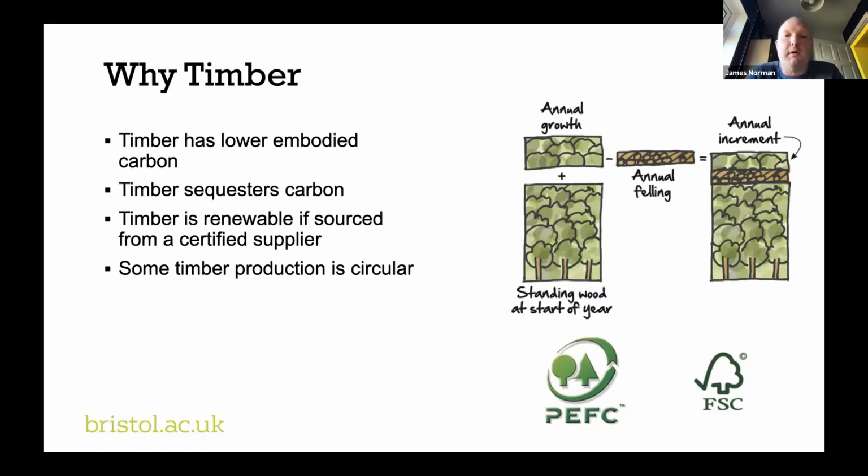Timber is renewable. As far as I can tell, except for straw, and I don't actually believe straw is a building material. It's an insulation material, but when you design straw bale, almost certainly you rely on other things to take the structural load, and the straw becomes insulation predominantly. So it's really the only renewable building material that we have. It's the only material that we can keep replacing as long as it's sourced from a certified supplier.